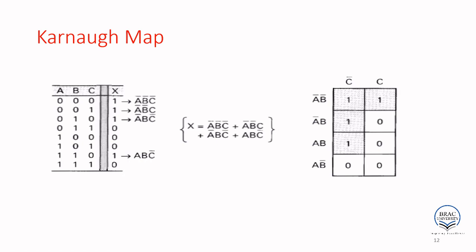So remember, your 1 0 is here, 1 1 is here, because if you look at the 0 and 1 values, it can change only one bit in a Karnaugh map. That's why after 0 0, 0 1, it becomes 1 1 to make the one bit change, then 1 0. So here it is C prime, so it is 0 and 1. Anyway, 0, 1, 2 and 6 are high, and the others are low. So this is the representation.